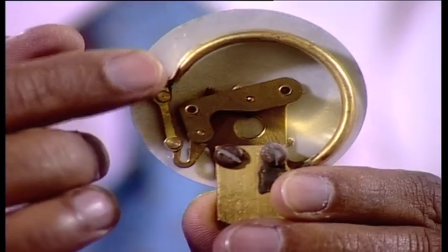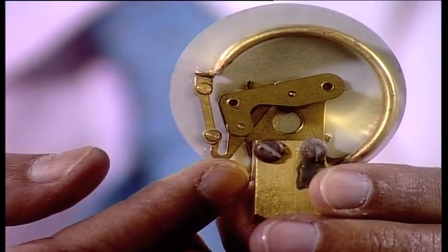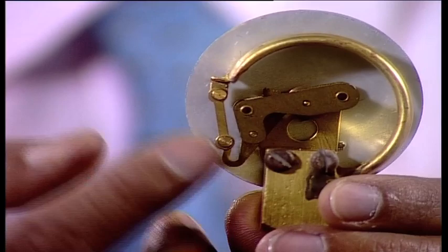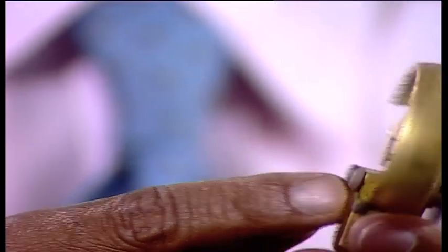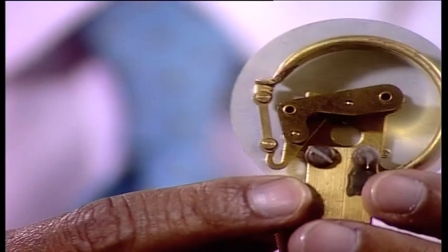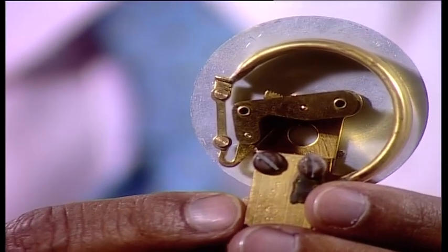So, you have a hairspring also here, which will bring back the needle, and there is a gear also inside, which you cannot see from the front, but from the back side you can. The needle is fixed on the gear itself, right. So, I am getting the output. This is about the C type Bourdon tube.